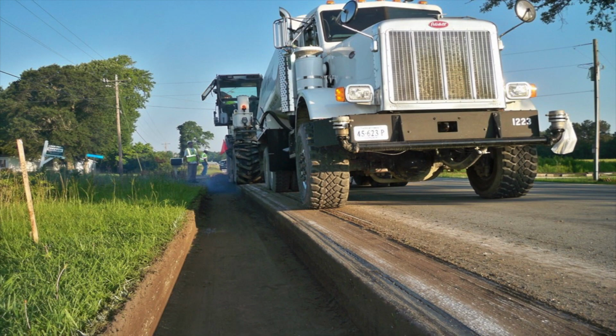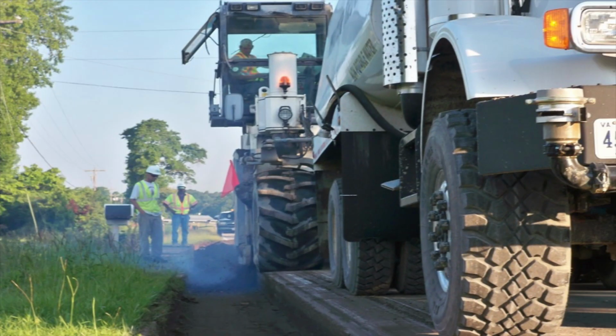So you have this section here that would typically be filled with stone, now backfilled with the reclaimed material from the roadway. There was plenty of material in the roadway to fall into the trench. This is pre-pulverization, if you will. We discussed earlier, we pulverized that roadway, and as the contractor came through, that material fell into the trench, and the contractor will go back and then incorporate that trench. So now you don't have that longitudinal joint. Everything is one homogeneous mix.